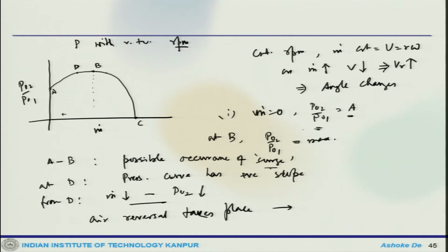Now, when the pressure downstream of the compressor falls substantially, the compressor can pick up again and repeat the same cycle. This occurs at very high frequency and is very detrimental to the engine, and this is called the surging phenomenon.